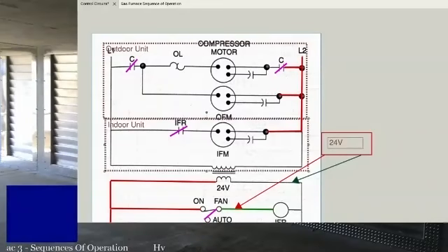It'll open really fast. Everything will apply power, the compressor will try to start, but it'll drive really high amperage, and then the overload will open. Sometimes you can keep that from happening by adding a start capacitor. But yep, that overload could be open, and that'll cause the compressor motor not to run for sure.